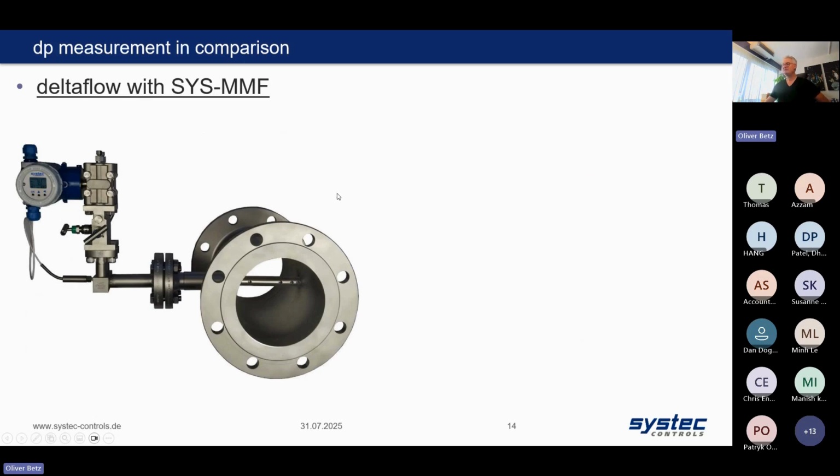So now let's go in comparison with the Deltaflow, in particular together with the multivariable. We also have a practically unlimited pressure and temperature range. We manufacture to all pressures and to all temperatures in your process. Not to all, but we made probes for 1200 degrees Celsius. We made probes for 600 bars in the offshore industry. So I would say this is an area which physically covers almost everything.